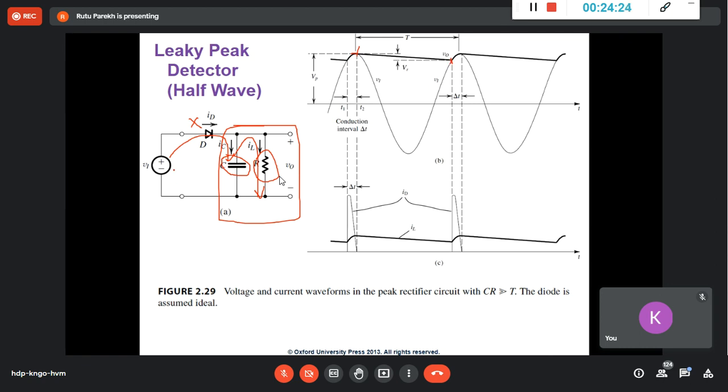So now, when this has reached 4.5 and then immediately 4.6, 4.7, will the diode be forward biased or not? Because this is 4.5 at some point here, let's say, and now the input has reached 4.6. So if it is an ideal diode, it will start conducting, right? Yes, ma'am. Yes, and it will charge this capacitor fully again.